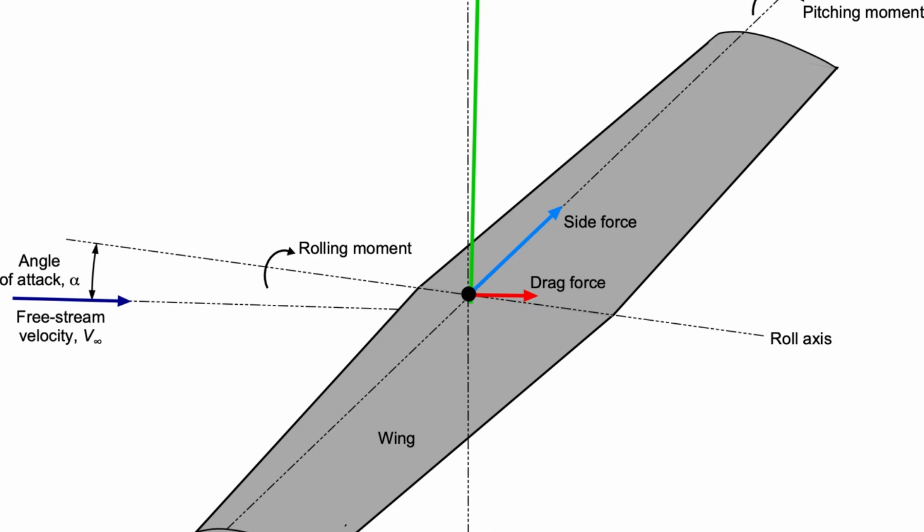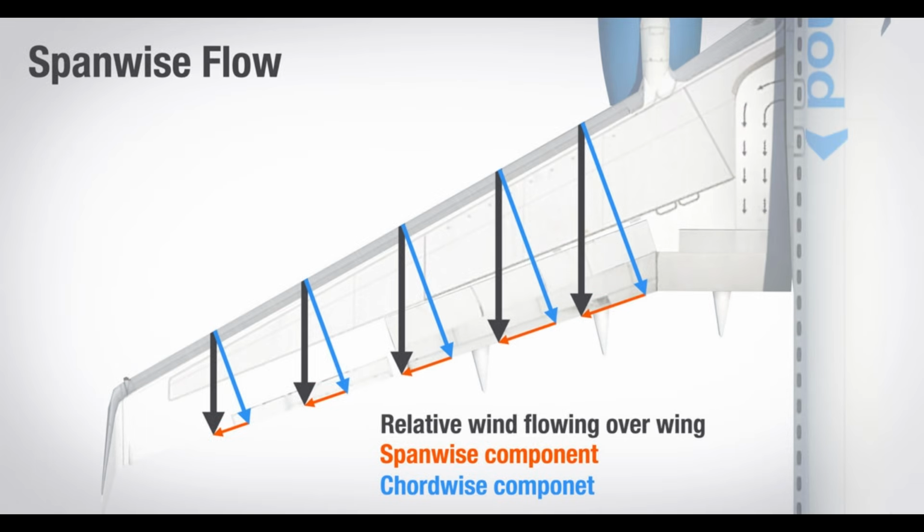At the time, swept wings were not widely accepted as a high-speed solution. They had been considered previously for structural or stability reasons, but not as a systematic method to control compressibility effects. Many engineers viewed sweep as a compromise that introduced structural penalties and low-speed handling issues. Jones's work reframed sweep as a deliberate aerodynamic tool. His analysis demonstrated that sweep directly addressed the root cause of high-speed drag rise rather than its symptoms.